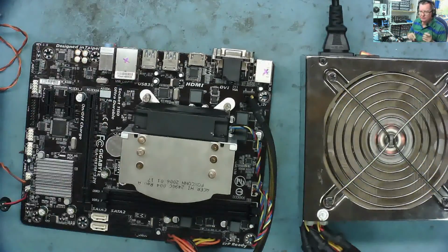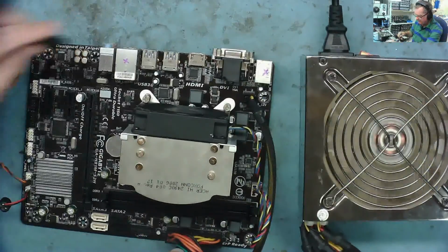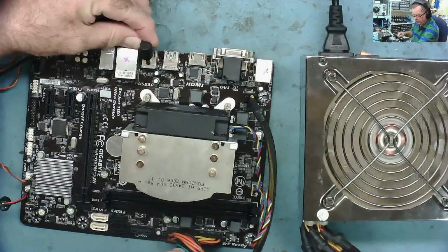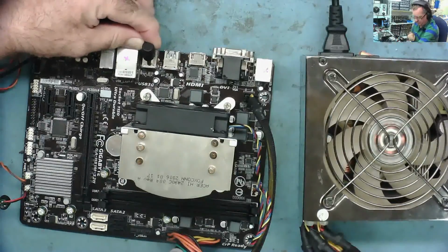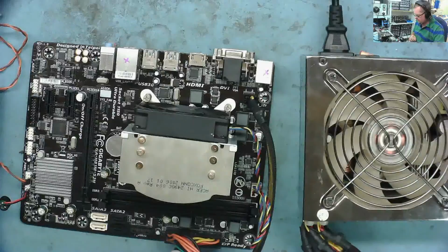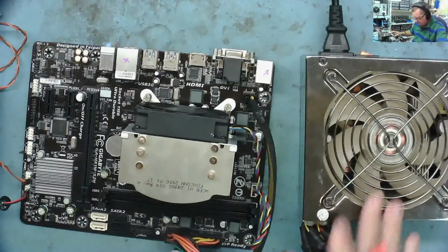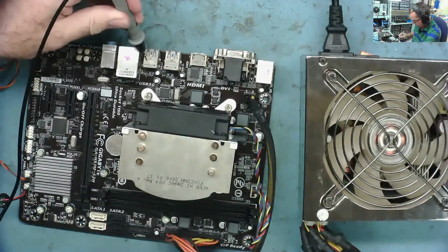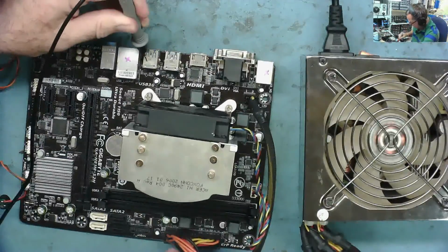But if I ground that green wire, this should come on and stay on, and this is what I don't understand. Ground the green wire, connect it to ground, and this should come on and stay on. And it comes on, and then just stops. It's as though something is tripping out in the power supply, if you see what I mean. If I now measure the voltage on the green wire with the power supply as it was, it stays low. Something in here is holding that low.